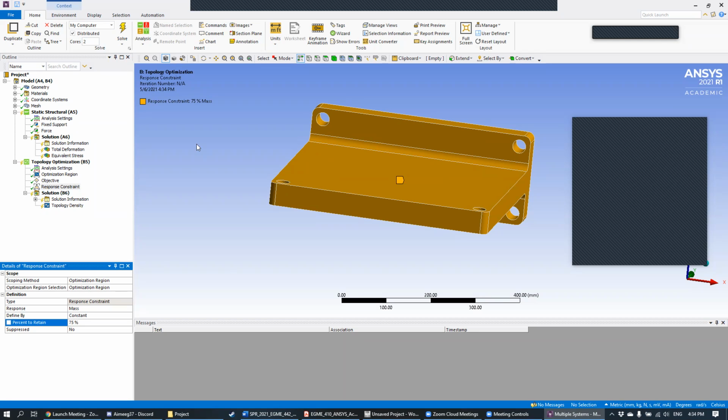What Ansys will do now is look at your model, run its optimization, and find the bottom 25% of this wall bracket that's doing the least amount of work, okay? It'll find that bottom 25%, cut it out of the model, and then give you a much more optimized geometry after that, okay? You can play with this, and today I'll test this out for different values so you can see its effect. Actually, for this particular activity, in its simplicity, this is going to be the parameter that has the biggest impact on our results. Okay. So any questions on this before we hit solve and see how this thing works?